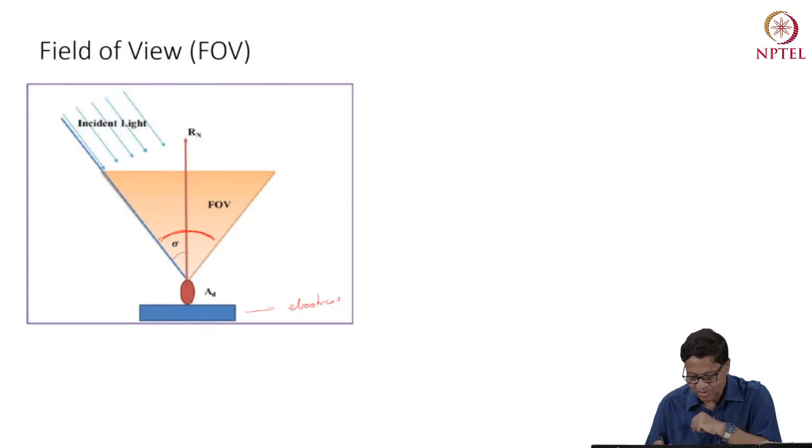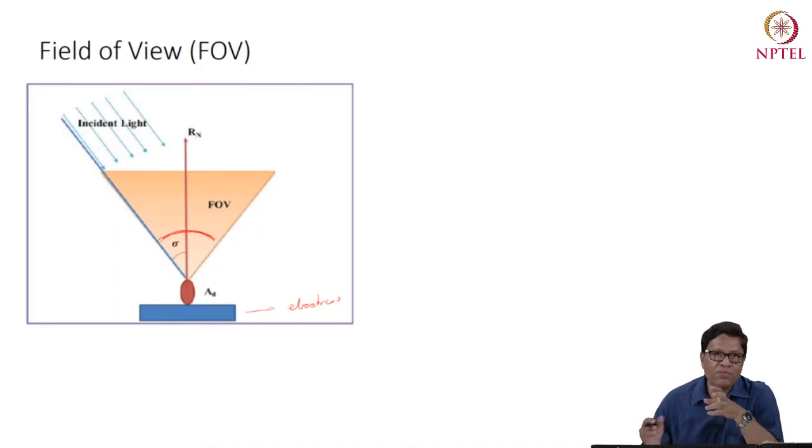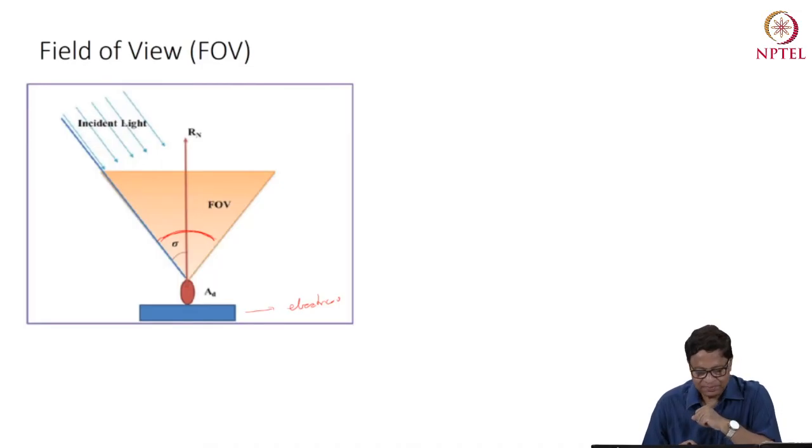So this cone or solid angle is referred to as the field of view. You can make the field of view very narrow, or you can make it wide if you want to collect light from all possible angles, and if it is a point-to-point transmission, you will try to make it narrow. So this field of view is very important when you're designing an optical wireless communication system.